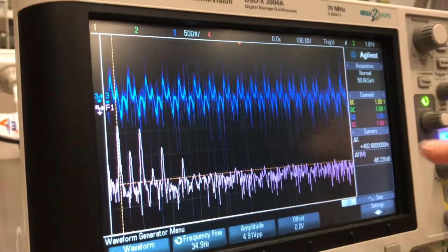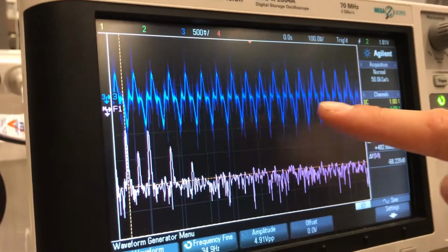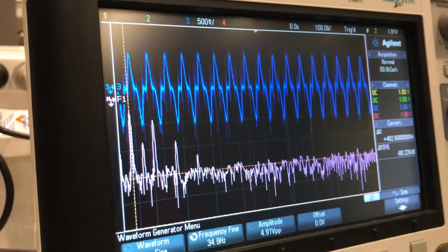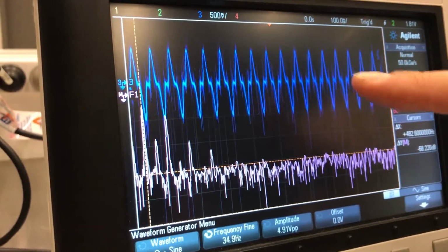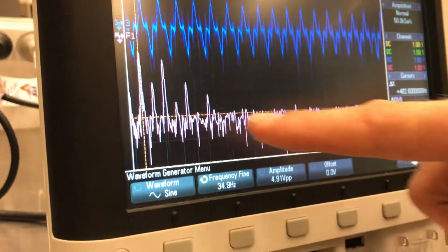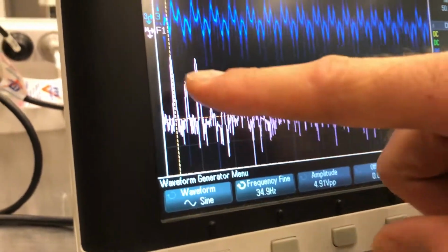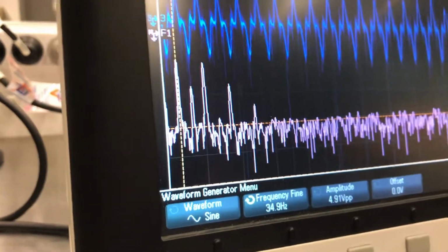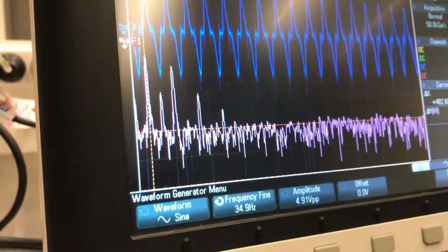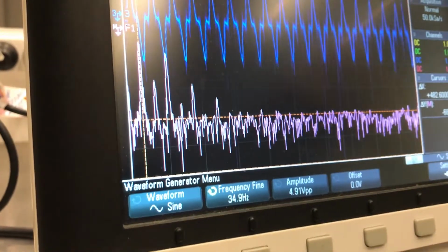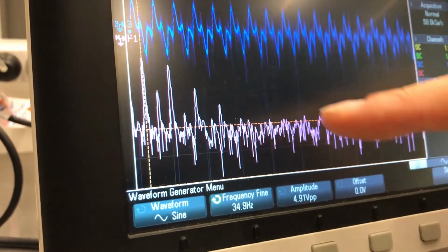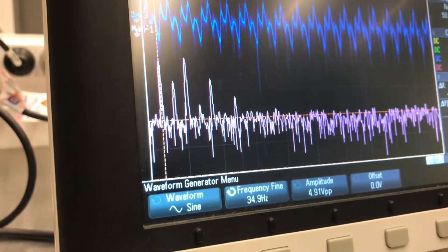If we look at the measurement that we make on the oscilloscope, we can see now that the measurement that we're making is modulated by the position of the laser beam on the vibrating beam, and in the frequency domain we get sidebands either side of the fundamental frequency as a result of the fact that the beam is moving backwards and forwards, and the mode shape is captured, or the operational deflection shape is captured by the amplitudes of these various peaks.